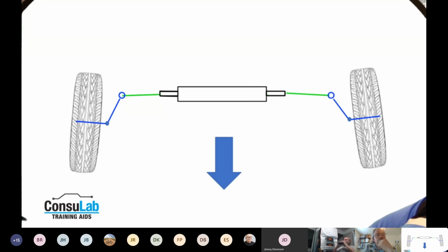And again, it can be a diagnostic thing. So a typical toe out on turns measurement is, again, there's a specification where you turn the turn plates X amount, measure the degrees on one side and the other, and look for the difference.